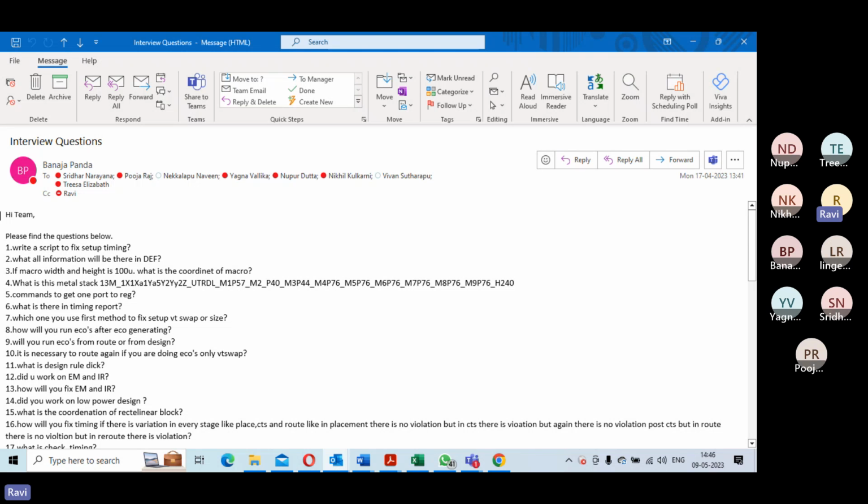Okay. Now, if this particular bunch of violation is in a location where it's highly congested, sizing is a problem, right? Then you can try swapping only and try to do some route or look at net fixing. Those are things you have to really smart script it. Are you understanding?